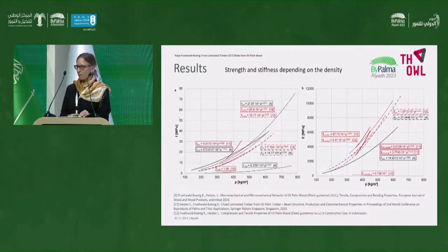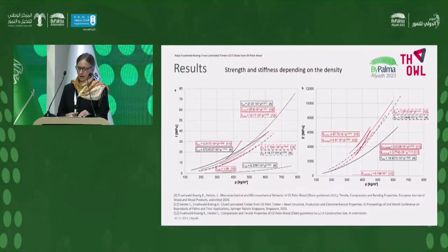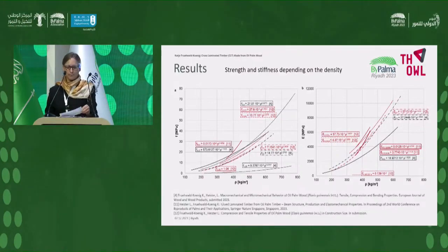There we have 1.9. And similarly, the ratio of the compression strength parallel to perpendicular is rising from 2.7 to 32.6 times. The compression strength parallel is above that of the perpendicular direction. And this is much higher compared to low-grade softwood, where we have 8.0.